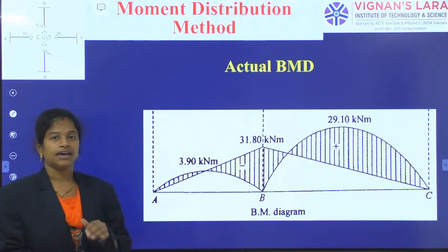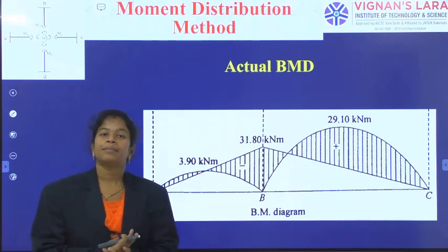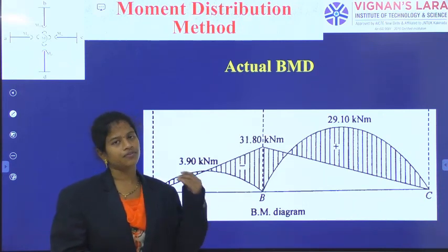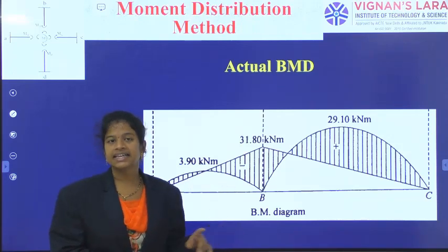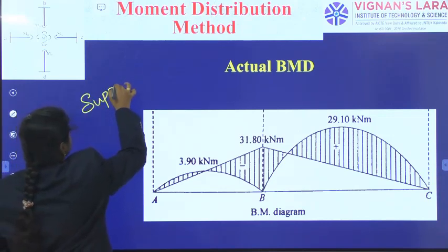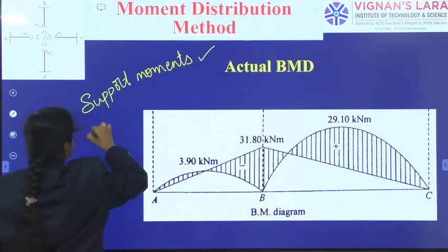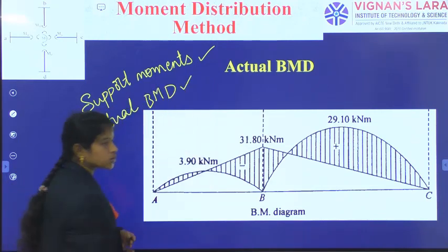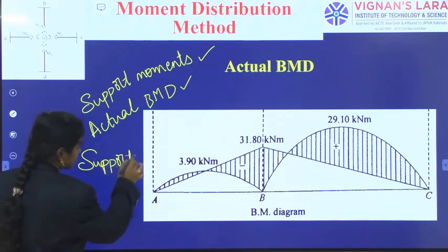Now I am going for the evaluation of the shear force diagram. But for generating the shear force diagram for the continuous beam or for any type of beam, I need the support reactions answer. Okay, so our next target is calculation of the support reactions. So we have done support moment calculation, and we have generated actual BMD. Okay, these two things were over. The next thing is support reaction calculation.